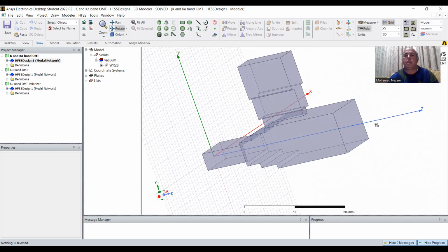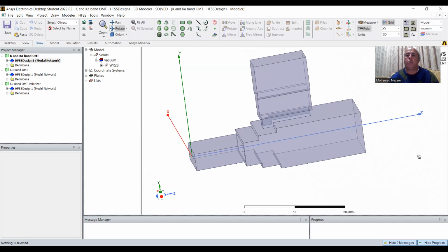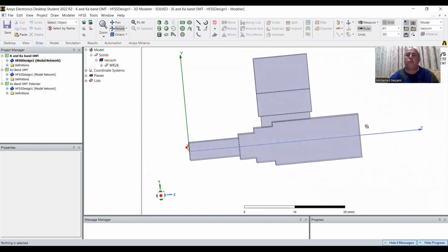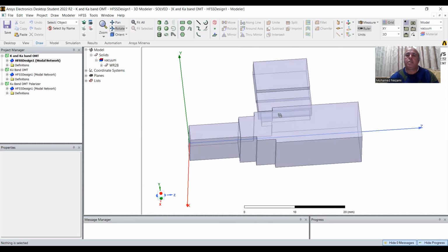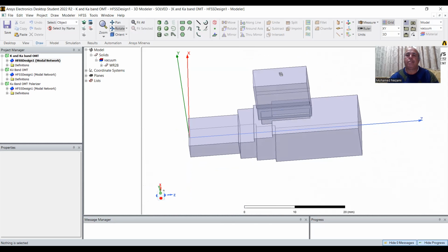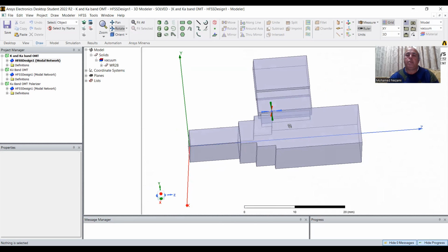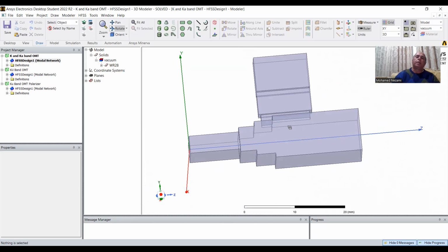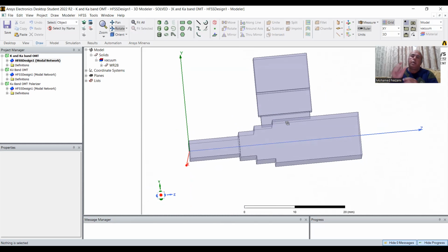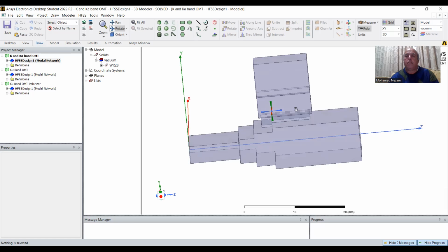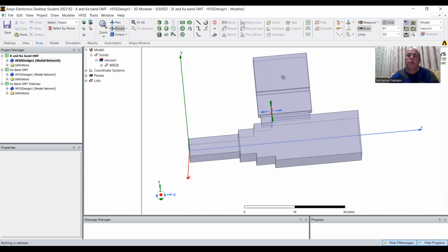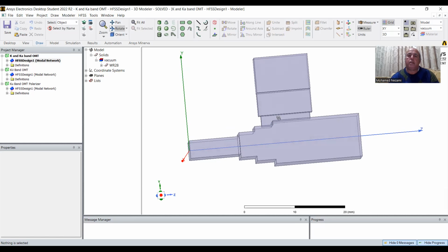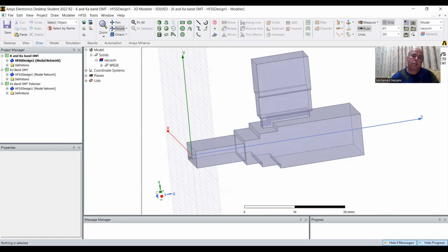So a circular polarized signal comes in here. This gets attached to the horn in here. The wave will come in and go in here, and there's a slot in this waveguide. There is an iris slot, a little rectangular slot designed with a specific length and width. The length is usually a half wavelength, so that it resonates at the desired center frequency. That signal goes out of here, and then the other signal will go out here.